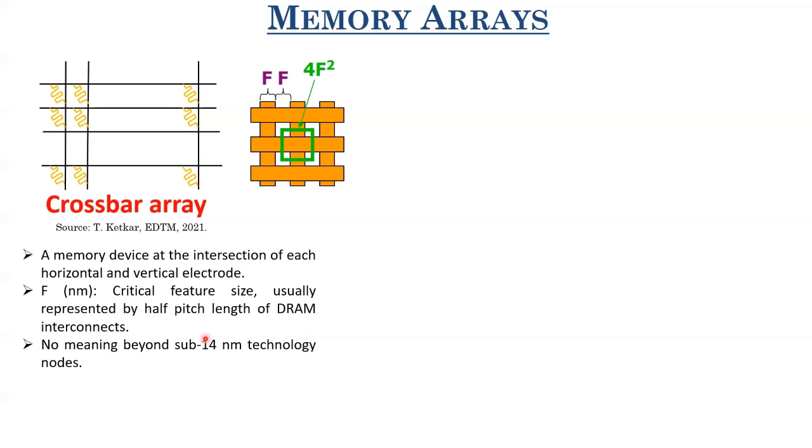Then from 14 nanometer, you multiply it with 0.7, it should go down to 10. 10, you multiply it with 0.7, it goes down to 7 nanometer. And there are also other technologies. So in between 10 and 14, there's also a 12 nanometer node, which is called the half pitch node. So these are just names. When industries were not getting sufficient advancements or benefits from 10 nanometer, they actually moved only the half pitch from 14 to 12. TSMC did that. So nowadays it's just a name.